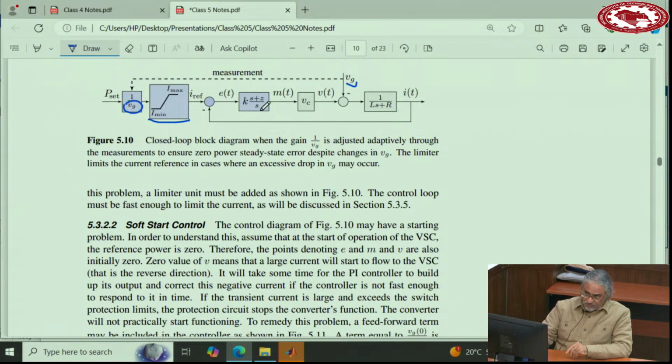And here, the tracking error is a number, but there is an integrator here. So this is 0, and it takes time to come up. Initially this is 0, but this is a large number. So if you subtract these two, you will get a large negative number here. This is the voltage across the inductor. So at the beginning, when you start, you have a large negative voltage.